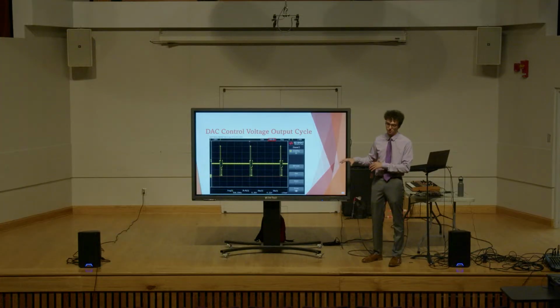And so now the sequential output from your DAC will look like a bunch of different voltage values. I also plugged in maybe 100 cycles of dummy values, so that's why there's that much blank space there, to simulate what my cycle time would be if I had 110, 115 different control voltages. And again, you probably can't see the resolution, but this cycle repeats once every 2 milliseconds, which is pretty fast. I believe this specific screenshot was taken before I started operating at the high SPI speed that I am now, so I believe it is a bit faster.